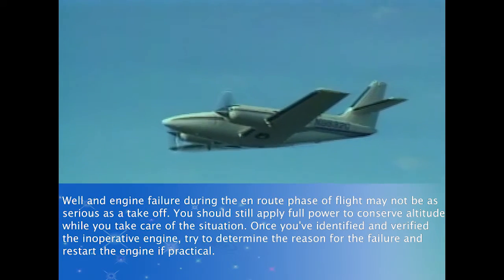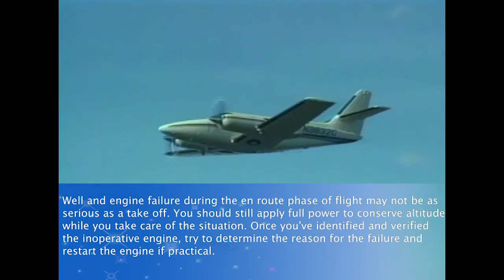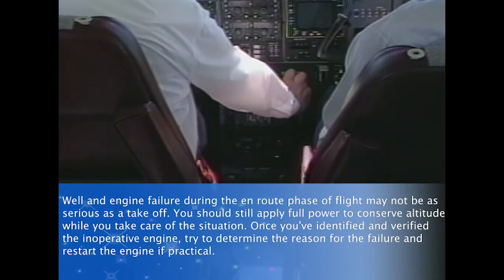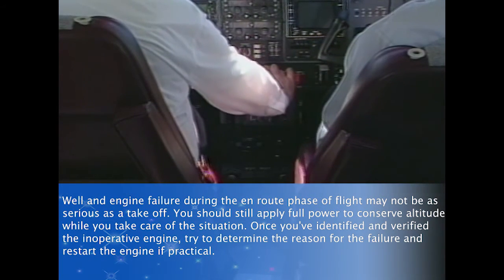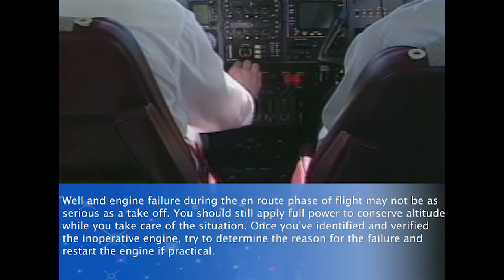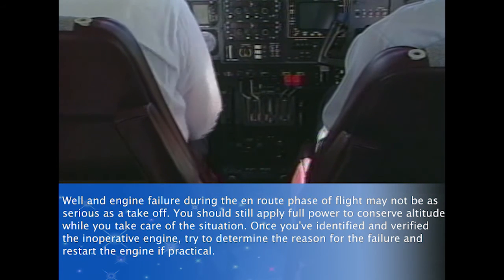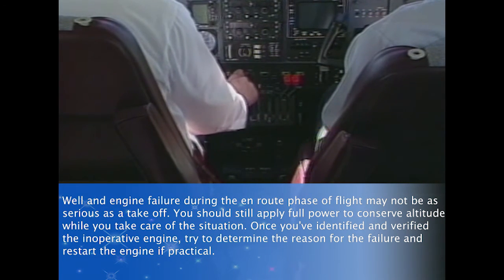While an engine failure during the en route phase of flight may not be as serious as at takeoff, you should still apply full power to conserve altitude while you take care of the situation. Once you've identified and verified the inoperative engine, try to determine the reason for the failure and restart the engine if practical.